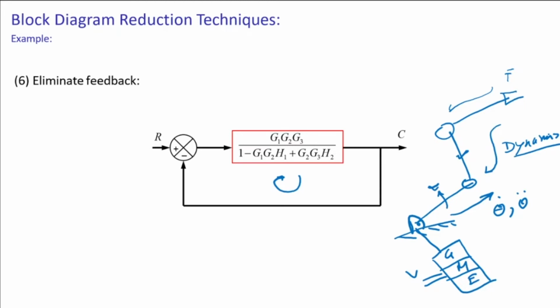And the controller here, the independent joint control, has no way of knowing the dynamics of the system. It is just controlling the joint based on the desired position it has to go to. This is a position controller. It doesn't know the dynamics, and there is no way of computing it. So what the dynamics does to the system is it starts disturbing it.